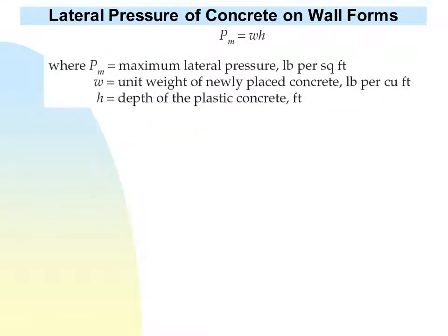The major issue when we talk about the difference between designing a formwork for a wall and a column, versus designing a formwork for a slab, is the load. The design itself will not differ at all, so you will follow the same design procedures that we talked about last time. However, the question here is whether the concrete is fluid or solid. So, the degree of fluidity of concrete.